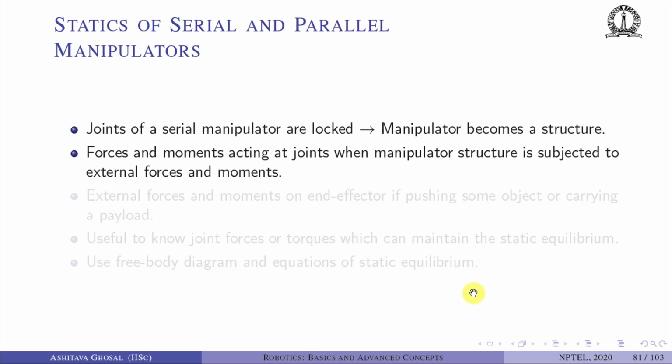The same thing will happen when we look at the statics of parallel manipulators. So basically, we are interested in finding out what is happening at the joints when the manipulator structure is subjected to external forces and moment. Remember, the joints are locked. The actuated joints are locked in a parallel manipulator.